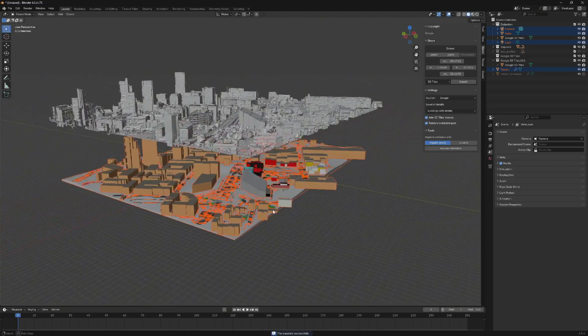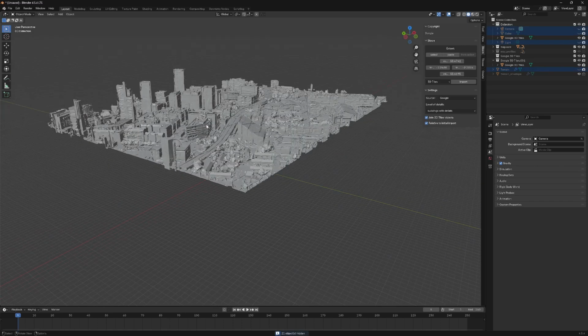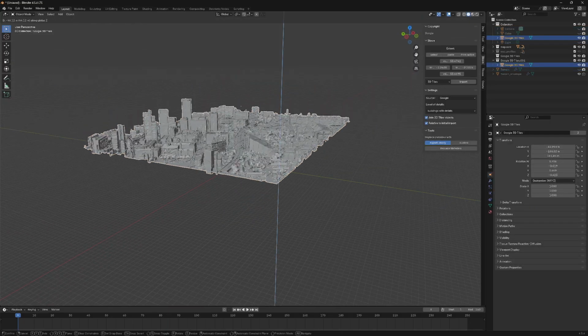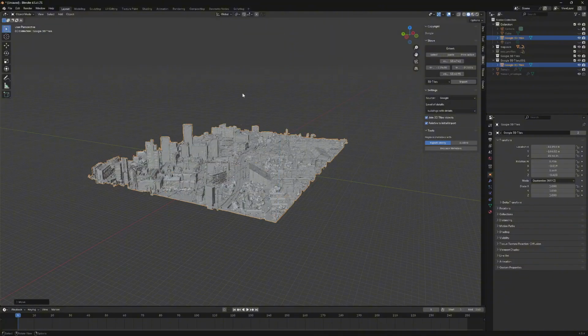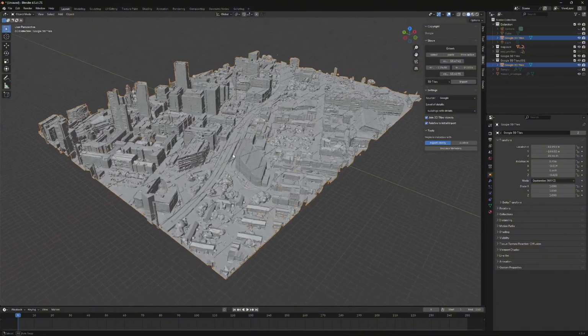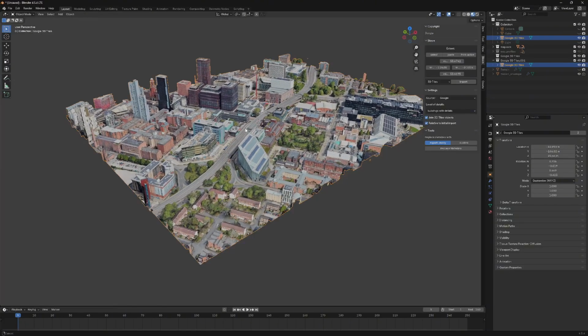and then I can export this file. Okay, great. What I'm going to do now is I'm just going to hide that. I'm just going to type H to hide it. And one of the other things that I'm going to do is I'm going to do G and Z, and I'm just going to bring this down because I'm going to show you now how we can bake the geometry into this file and bake the textures so that when we bring it into Rhino, it brings the textures, because by default, it won't bring the textures.